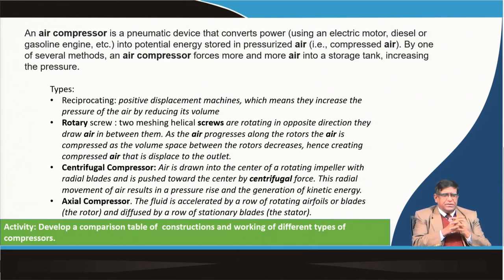Now, the reciprocating compressor works on the same principle as your reciprocating pump, which you studied even in your school days. It is a positive displacement machine in which they increase the pressure by reducing the volume of the air, with a piston's movement. In a rotary screw, two meshing helical screws rotate in opposite directions, and then the air will be trapped, pushed, and compressed in the container.